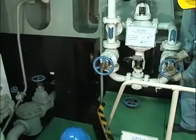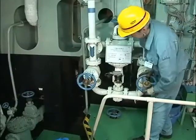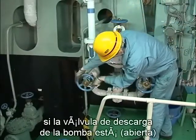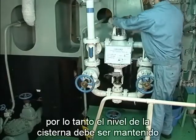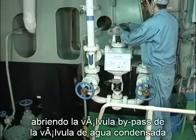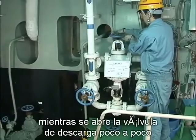At the start of the pump, pressure inside the main condenser is the same as the atmosphere. The hot well level will drop if the pump discharge valve is opened. Therefore, the hot well level must be maintained by opening the condensate water valve's bypass valve while opening the discharge valve little by little.